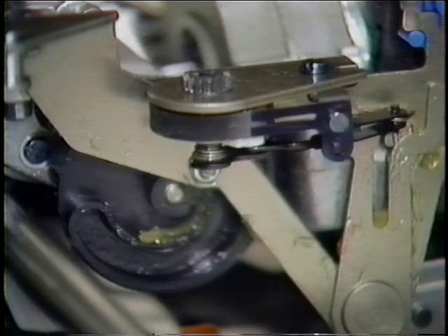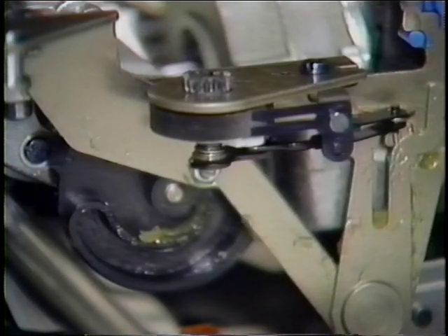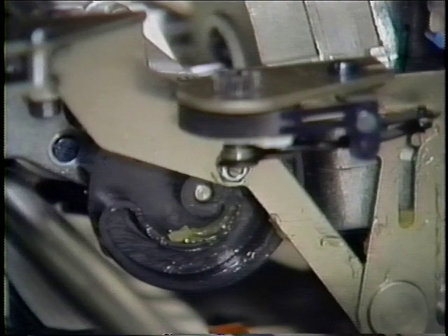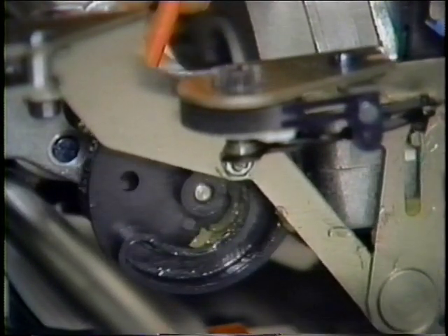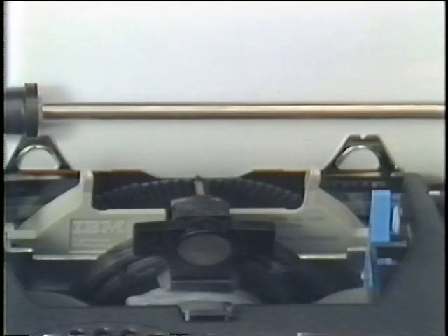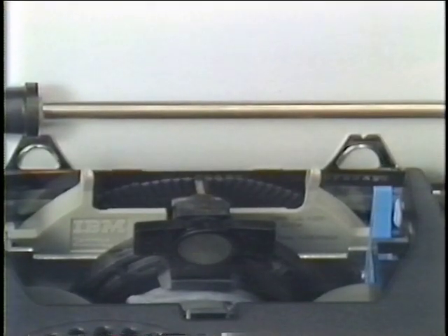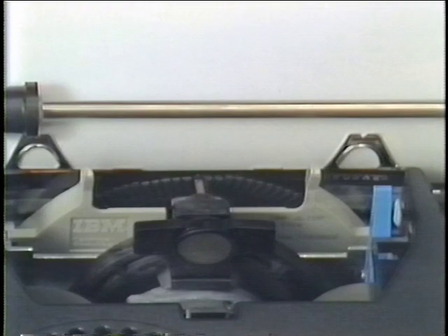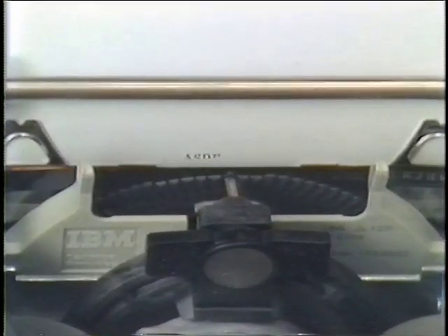During POR, the printer board drives the ribbon lift motor through a complete lift cycle to ensure it is working correctly and that the lift cam will be in the home position before typing begins. When POR ends, the ribbon lift motor is held electrically detented by the printer board. If the lift cam is moved away from the home position, it will cause print problems.